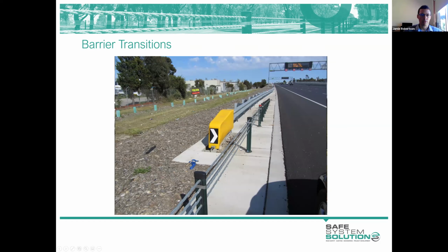In this case, the points of need are overlapped. The distance between the two systems is questionable. The desirable thing to do is to provide for the width between the systems to be at least as much as the dynamic deflection of this upstream system. So in the case of a wire rope, we're talking 2 meters or thereabouts minimum.